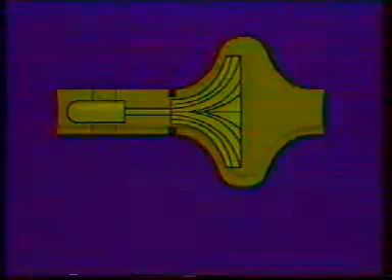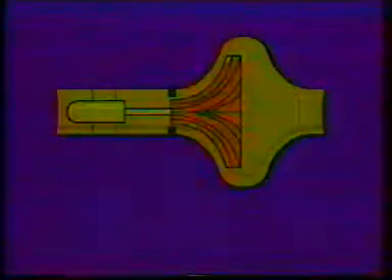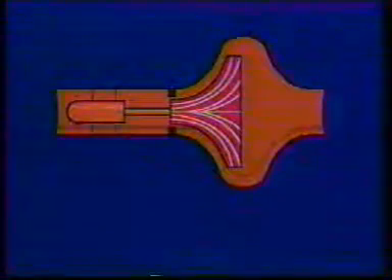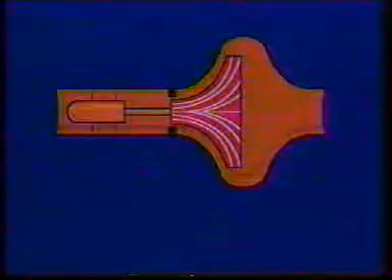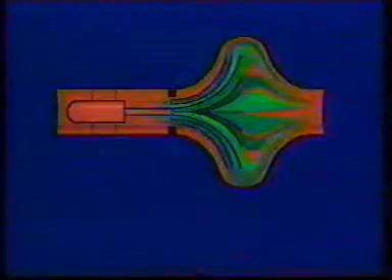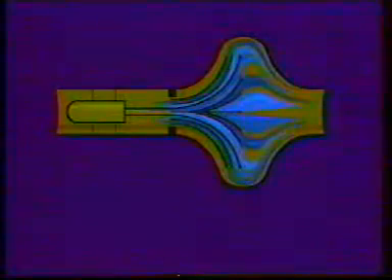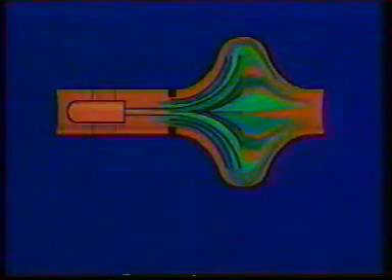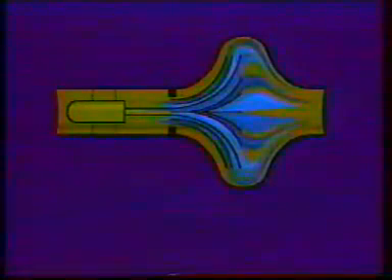This illustration shows one type of Coriolis mass flow meter. It consists of an impeller with radial vanes positioned so that the vanes are in line with the direction of flow. A small motor turns the impeller at a constant rate. The vanes guide the flow in a direction that is radial and perpendicular to the axis of rotation. As in the case of the person on the revolving platform, this produces a Coriolis acceleration, which in turn exerts a force on the vanes.